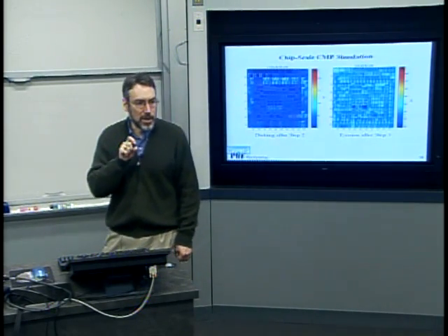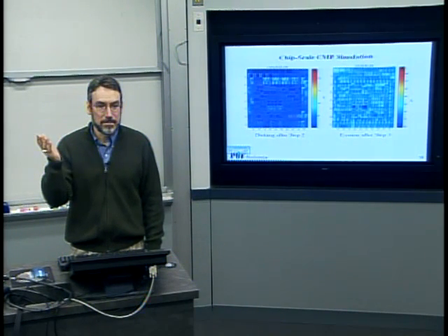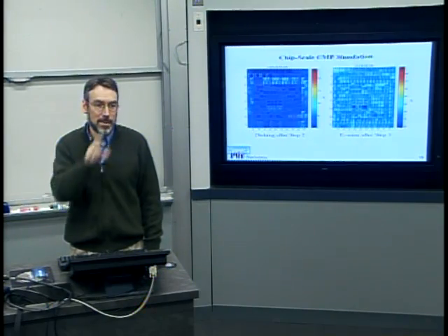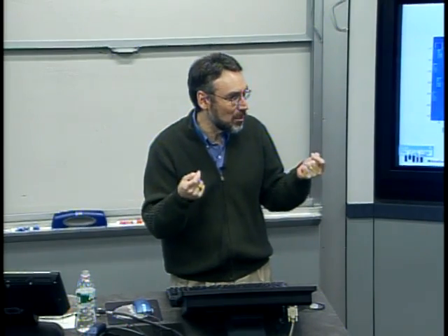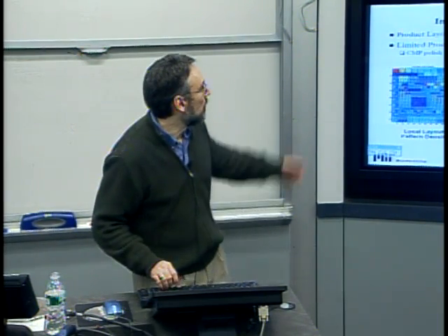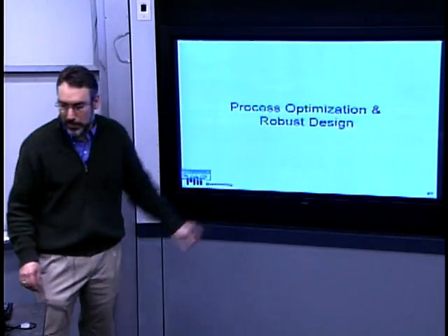And that could be very important because the thickness of a copper wire determines its electrical resistance. It even affects the coupling capacitance between two neighbor wires. So those key electrical parameters, resistance and capacitance, that determine interconnect speed depend on that critically. So that linkage with robust design can be very important. One can also use those kinds of models to play with process parameters and empirically, as a function of the process conditions, minimize these systematic sources of variation.